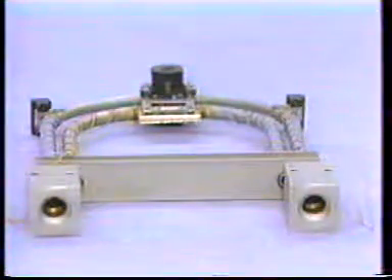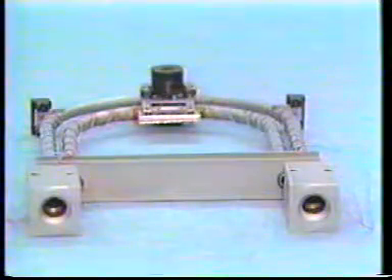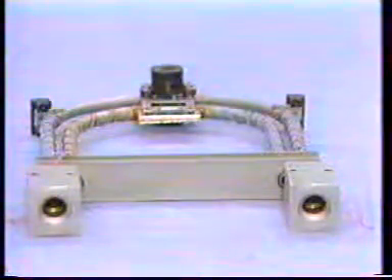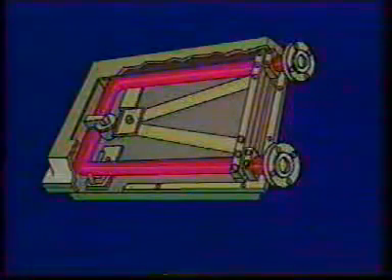Another type of Coriolis mass flow meter has a U-tube design. Let's look at an illustration to get a better idea of how it works and measures flow. This Coriolis mass flow meter consists of a U-shaped tube. Process fluid flows through this tube. As it does, an oscillator vibrates the tube rapidly along the axis formed by its open ends. The resulting angular motion is equivalent to the rotating platform we saw a moment ago, and the flowing process fluid is equivalent to the person attempting to walk toward the edge.